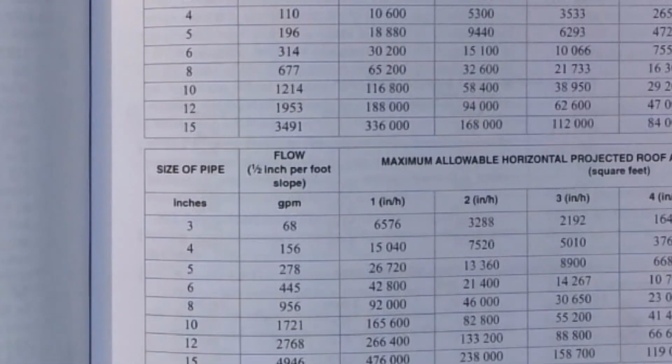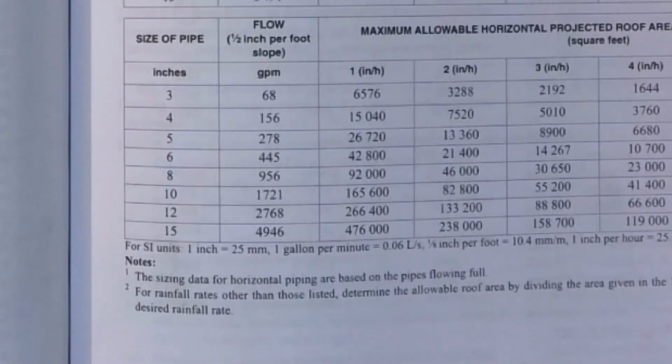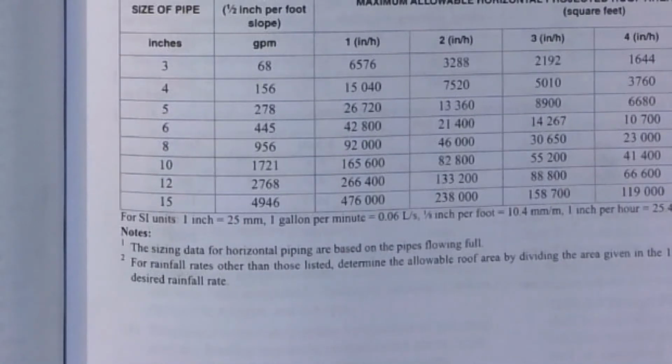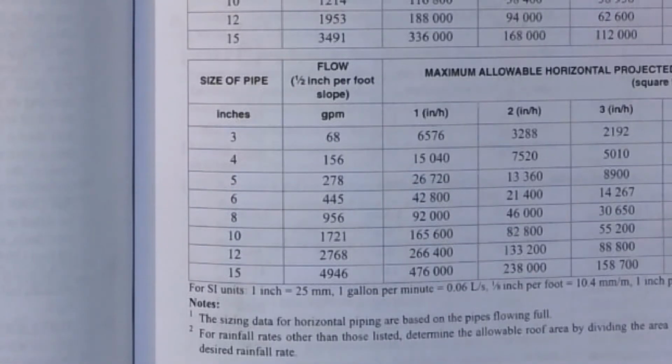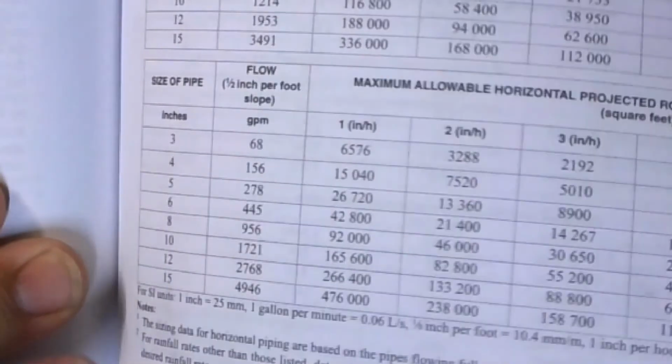Let's see, what else can I tell you? All of this, the sizing based on gallons per minute, is the easiest way. There's 2 different ways of doing this. The easiest way is just taking your gallons per minute. But in order to do that, you still have to find the square footage of the water that's going into that section of piping, into that roof drain. But, and we're going to talk about this briefly, and then we'll end the lecture for the night.